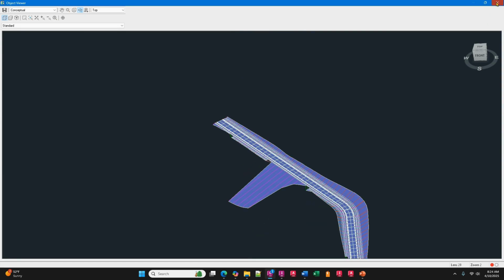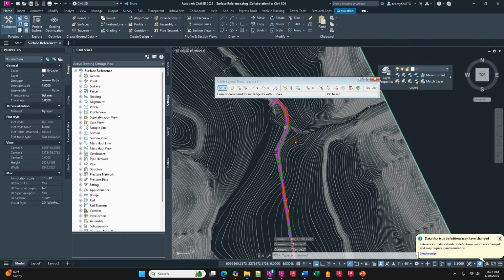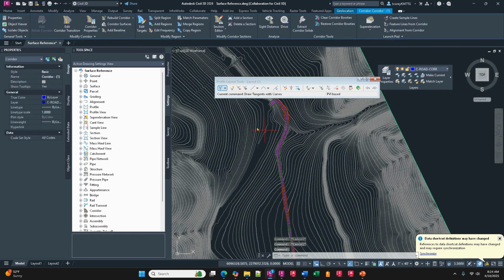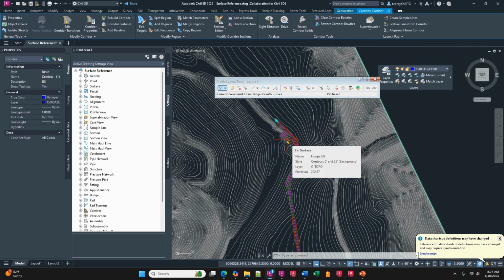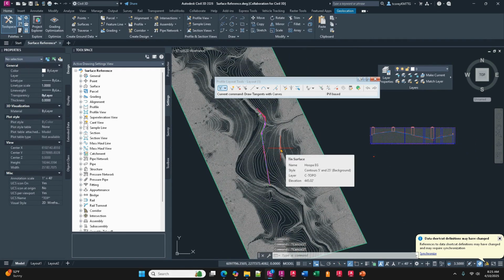I'm not going to do it because we're getting a little short on time, but I do want to point out in this version of Civil 3D, your corridors have ability to do corridor transition where I could go in and say, okay, from here to here, change that fill slope from 2:1 to 4:1 or 1:1, I mean, or whatever. Okay. So just keep that in mind. We're not going to show it now. We'll do that in another seminar.